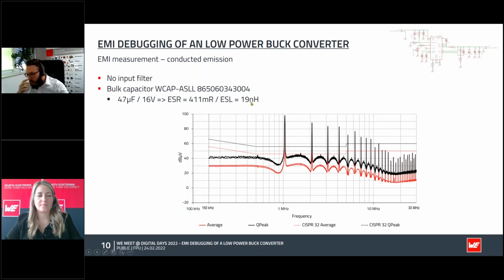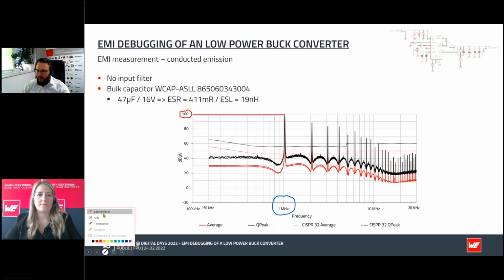Also, you can get these parameters from our online tool. So from REDEXPERT, you can really move sliders to your voltage, frequency, and so on to get the values here, especially the ESR. For ESL, it's not shown in REDEXPERT, but you can calculate it based on the impedance. And the second place where you can get the parameters is from LTspice. Our products are in LTspice, and there you can also get the ESL value.